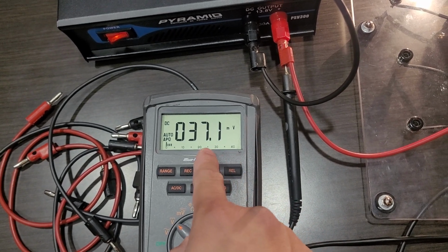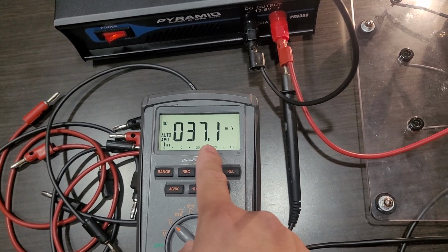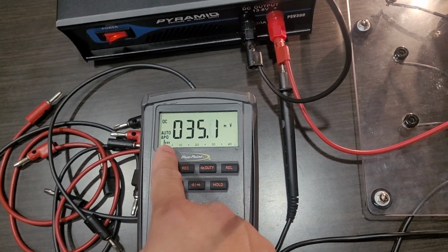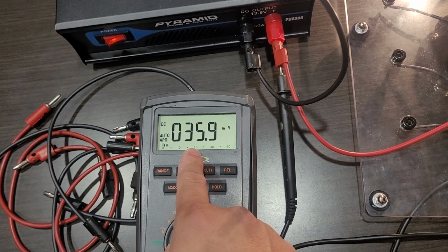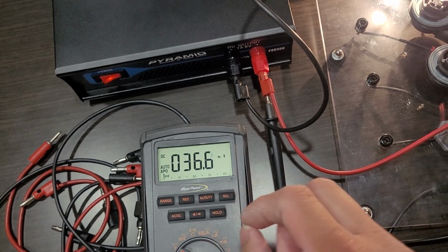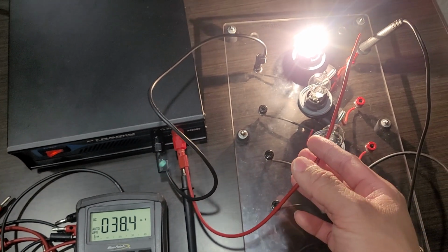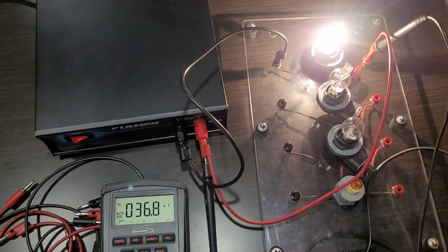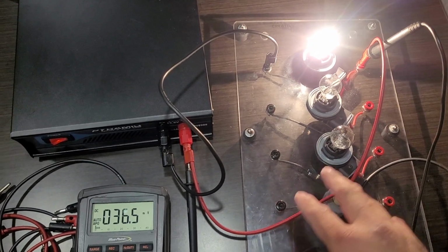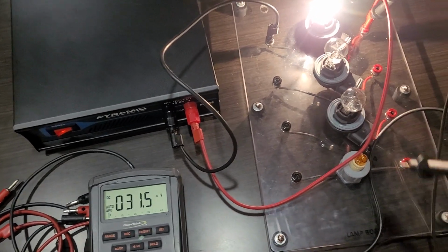And if I wanted to convert it over to actual voltage, I have to move it 3 times to the left, which means 1, 2, 3, which will end up being 0.0, and right now 5.9 volts. Okay, so again, this is a millivolt reading, very minute, which means this wire right here is not using up a lot of voltage, which is ideal. You don't want it to. Had it been using up an actual voltage value, the light bulb here will receive less. Therefore, it will probably be dim.